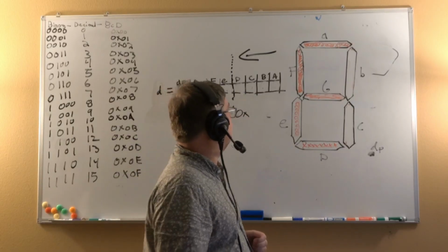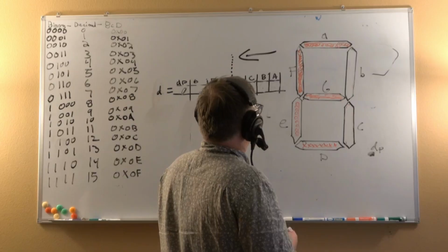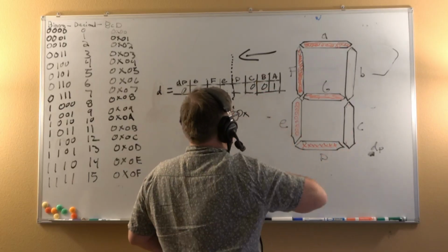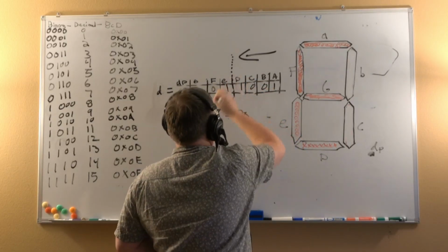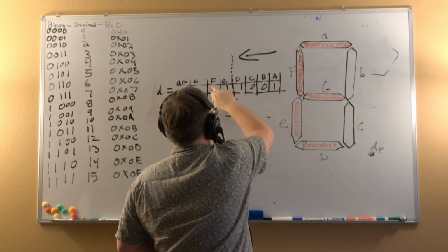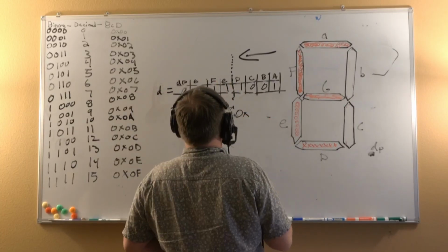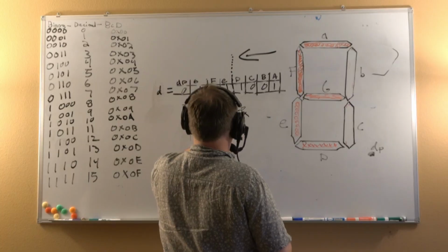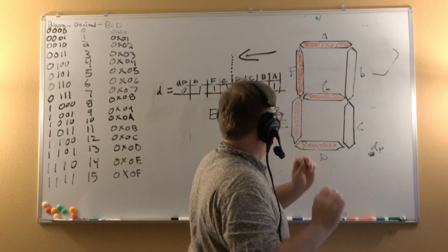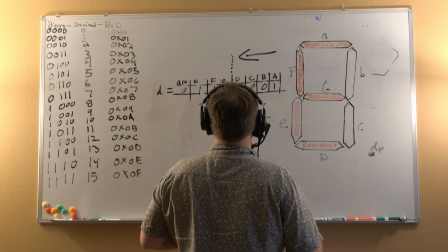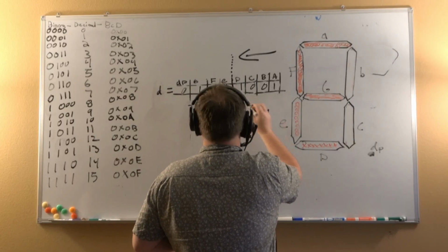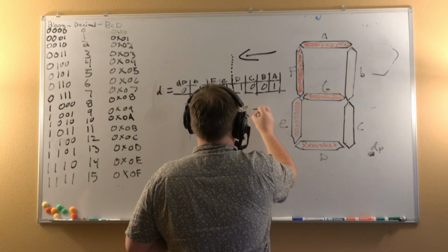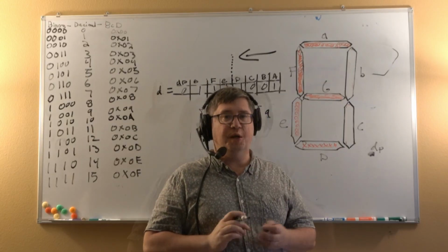This one's the E. The E is pretty simple, because I think they're all pretty simple. So once again, red 1, B 0, C 0. You don't see nothing there. D 1. E, there's something there. 1. F is 1. G is 1. Decimal point is always going to be empty, so it's going to be 0. Okay, hold on. Wait. So now let's go ahead and do it. That's definitely a 9 right there, and that is a 5, 6. That's a 7. 0x7.